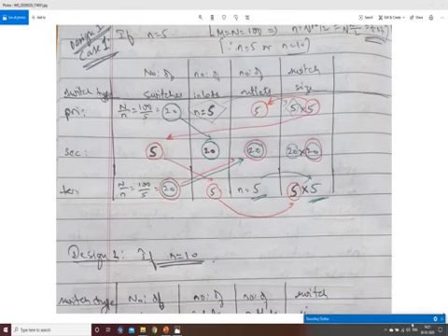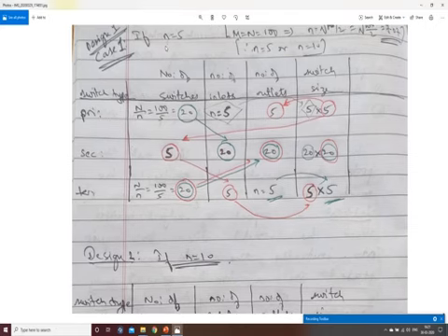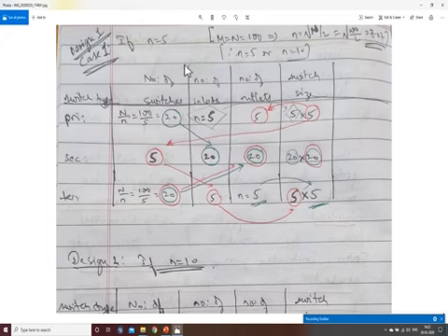Here we can see that we have a solution for the two designs. If I consider n is equal to 5, what is the number of switches required and what is the switch size? These are the two parameters I have to decide. How do I decide on these? I know that m is equal to n is equal to 100, and when I estimate, I got these values, and the factors close to these values that are factors of 100 are 5 and 10. If I consider n is equal to 5 and proceed, here I am just giving what type of switch is present, that is primary, secondary and tertiary.